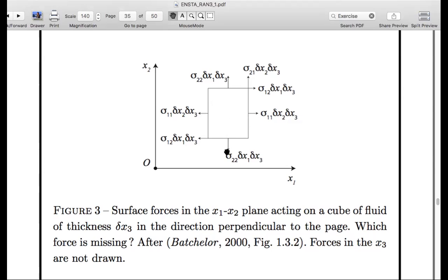Actually, let's go down here and talk about this surface here. But before I do that, I just want to talk about Newton's third law, and also about conventions here. So the normal is pointing upwards here. And so I have a little box, or a parcel of fluid that's in the shape of a box. And so I've drawn all my normals in the outward direction. That's a typical convention. You could say at the start, I'm going to consider the inward facing normals, but the standard is to choose the outward facing normals. So that's why these normals are all pointing outwards.